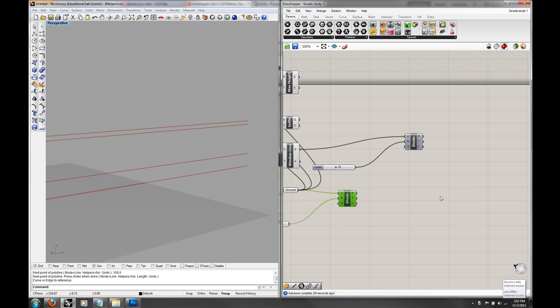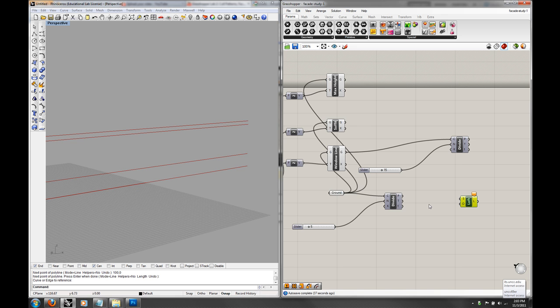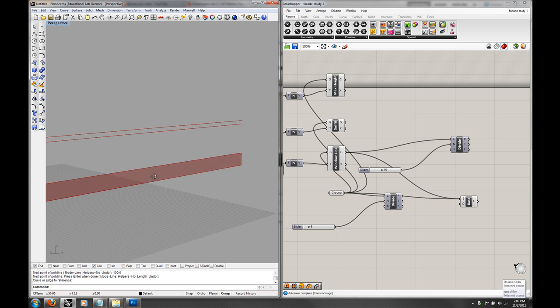Okay, a way to create geometry that is useful when you have two lines is to create a loft between them. That's going to create a surface. So we make a loft, and we want a loft from the ground to the window line, and that's going to be our base. So let's call that loft base. So connect the ground line, and then remember I have to hold shift, and I connect my window line to the base, and that's going to give me that geometry.